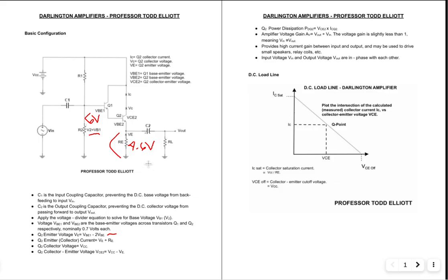The purpose of having two transistors, that's what gives us the current gain. So whether you're looking at the beta AC, the AC current gain, or the beta DC, the DC current gain, by cascading them together, the betas actually multiply. So that's why, whether on the AC or DC, we can have lots of current in the collector and only a little bit of current in the base of Q1.